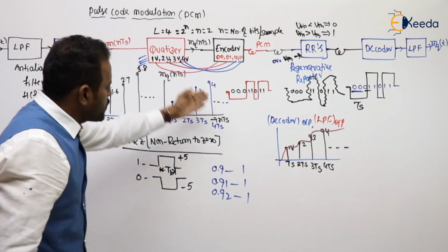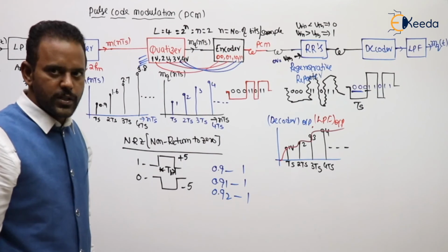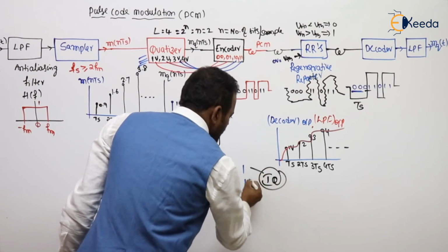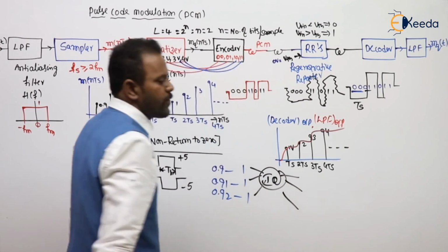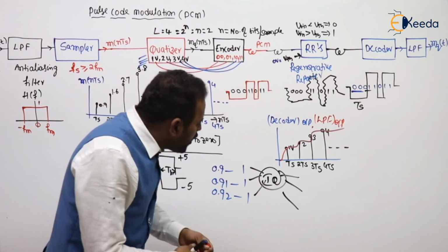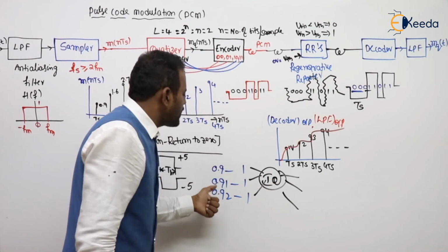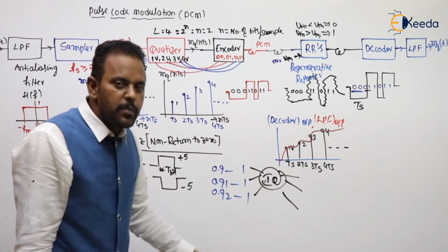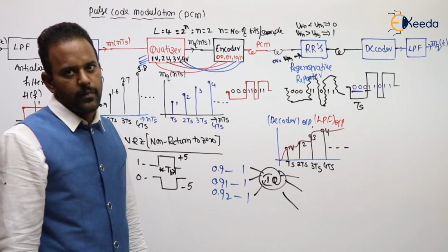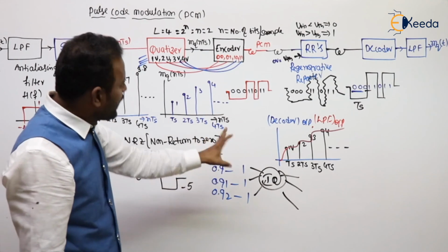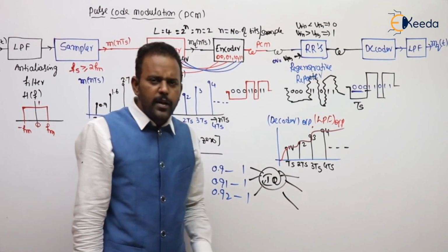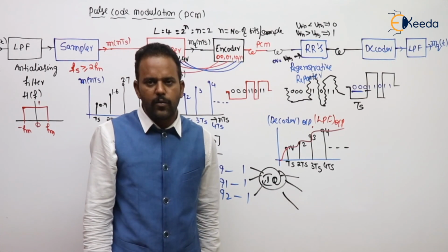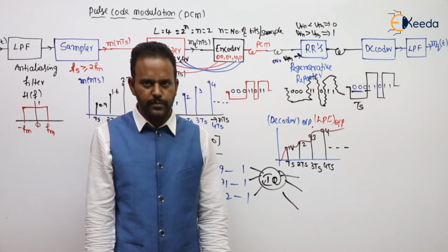Here the system is producing the same output for different inputs. It means if I design the inverse of the quantizer, it takes 1 but it has to produce different outputs. How will the system know whether to produce 0.9, 0.91 or 0.92? Because whatever the value here, it is receiving the same input. Are you getting my point or not? So that's why quantization is irreversible. Because of that, some quantization noise will be there. We'll try to maintain that value as low as possible.